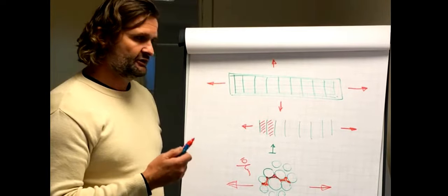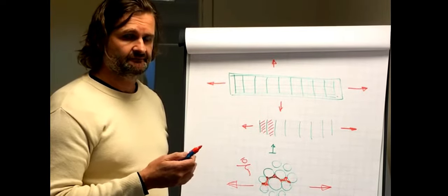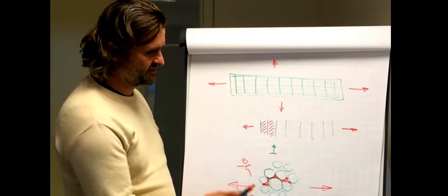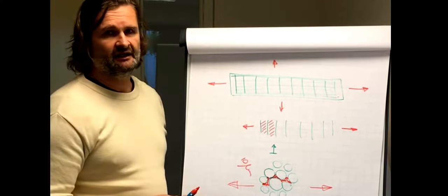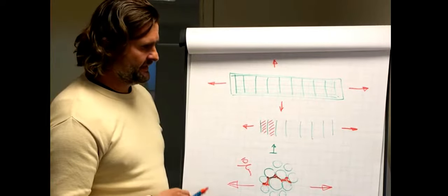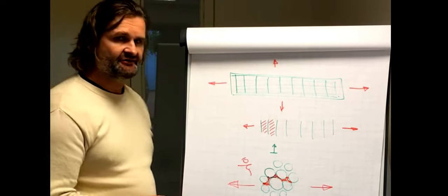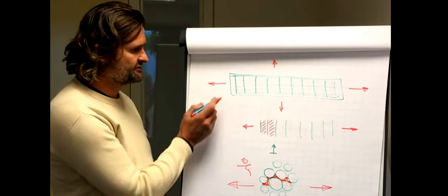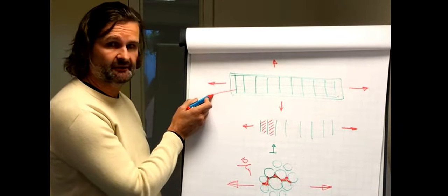So there's only very limited effect of what we can do with toughening resins, because inside a laminate it doesn't do much. The driving factor for the stress level that creates microcracking is the E modulus of the horizontal fiber. This.